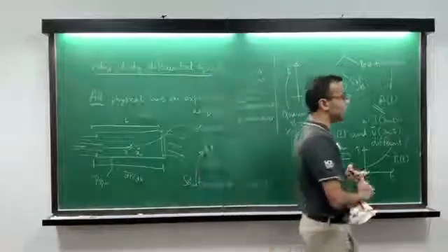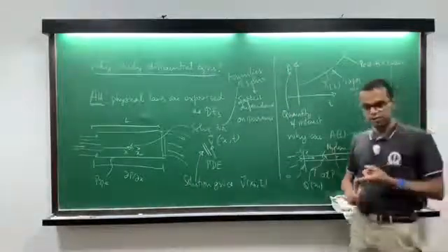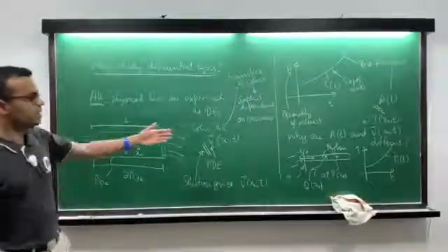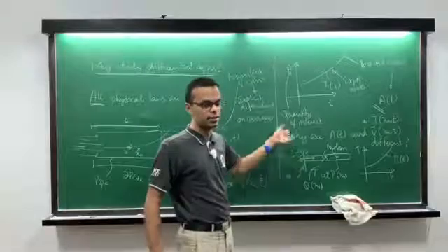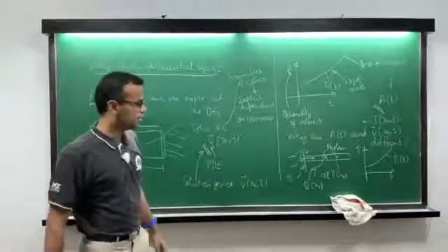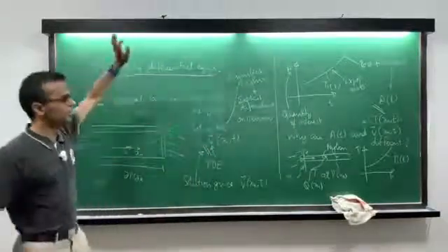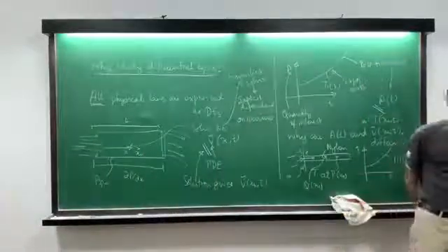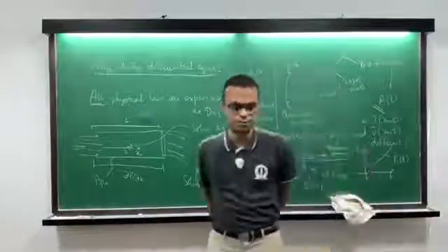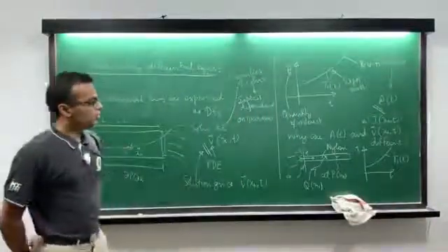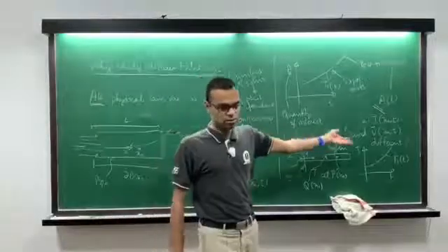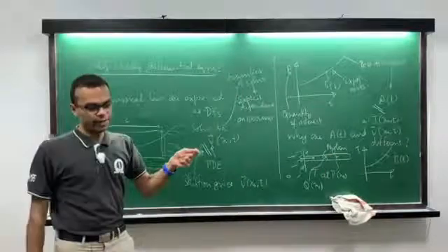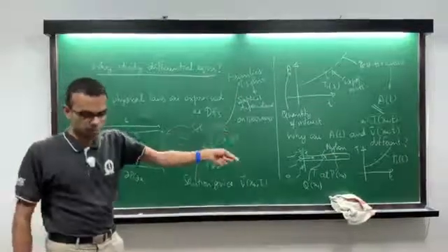I know what stuff I'm leaving out. I know what stuff I'm including. I know what the approximations are, and so I can tweak those parameters in particular when I change the material, change the cross section, change the heat content, change the boundary conditions, whatever, right? So now I know, for instance, if I went through this entire process, that the only thing that matters here is what is called the thermal diffusivity, usually denoted kappa or alpha or something. And so once somebody comes and tells me this bar is made of nylon, steel, aluminum, copper, whatever, all I have to do is get that value for that particular material constant.